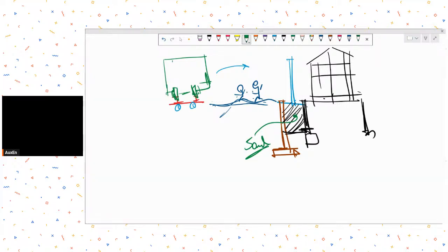We have done such things in our industrial buildings. Of course, it did not have a problem from rail vibrations, but just because it had a problem of vibrations from the nearby buildings, that's why we had done such a thing. So maybe in this case also, you can come up with such a scheme where you try to have a pit all around the building and try to fill it up with sand. So at least the vibrations that are transferred from the railway track are sort of isolated by this sand layer. Okay. So this is what comes to my mind.